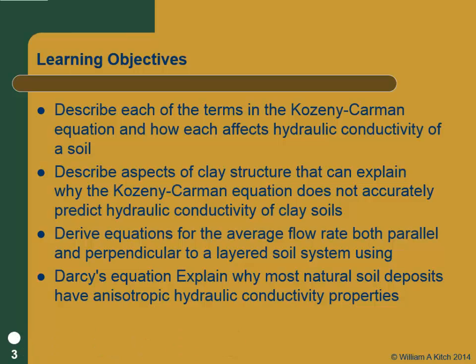We're going to talk about Kozeny-Carman, and I assigned a paper for you to read on Kozeny-Carman as another way to get hydraulic connectivity from coarse-grained soils. And we're going to talk about it theoretically because I think it's a nice basis for understanding the soil structure and mechanics of soils that control hydraulic connectivity.